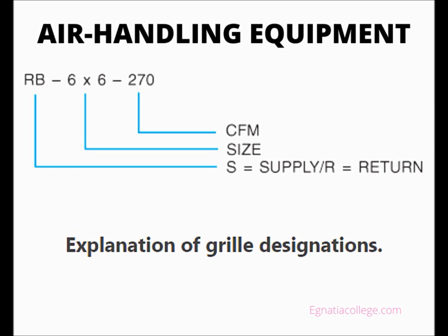A separate ventilation system removes stale air from each room of the school. All the rooms in the addition except the smallest closets and the stairways are provided with a system of ducts and a fan to ensure air circulation. A louvered grill in the room receives the air and channels it into a duct that carries it to the roof, where a fan exhausts it to the outside.